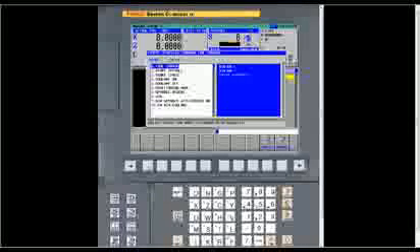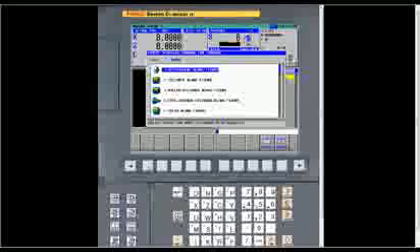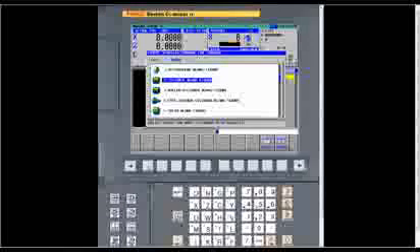If you press that soft key, it takes you into this. You have two tabs. The start lines, which will be the fixed forms, are in tab 1. Then if we arrow over, we have blank definition. This is important because typically at the start of the program, you'll do a blank definition, and this is basically for the simulation. When it does the simulation, it'll show a part that's representative of the piece of stock that you're machining. But again, this is very simple stuff. Just fill in the blanks.